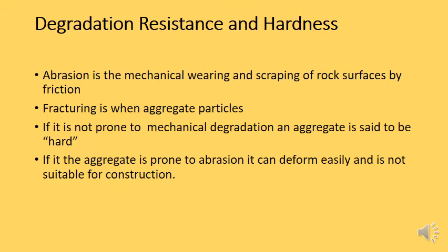Well, hardness is not a measure of how strong a particle is. It's not a measure of how much strength or force an aggregate can withstand. Hardness is actually about how resistant an aggregate is to abrasion and deformation and brittleness, if you like.